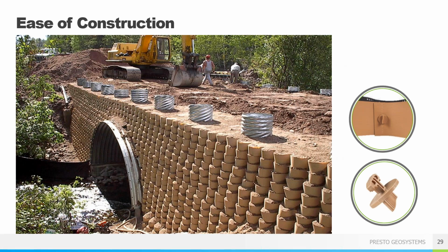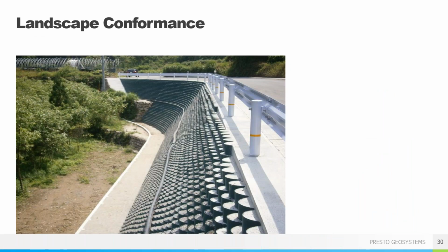Very flexible system, as I mentioned a couple times now. The panels are, like I said, 100% HDPE. They can accommodate any type of construction around, say, culvert pipes, which is shown here in this slide, and also pipe penetrations here for roadway conditions. Basically, they're putting some metal tubes in to put some foundations down for some guardrails on a highway. You can just see the entry and all those pipe penetrations. So we have details for that, so we can help you with that also.